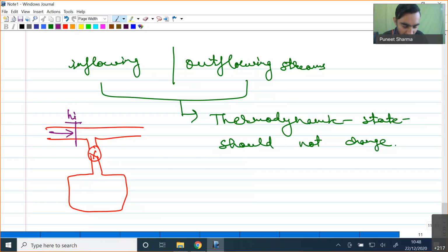Because while we integrate, we are only considering the variations in the mass flow rate. We may have variation in the mass flow rate with time, because we obtain the overall Mi as integration of Mi dot dt. So if we have variation of mass flow with time, that can be accounted for in this overall mass calculation equation. However, we are not doing the integration for finding the change in state of the thermodynamic property.